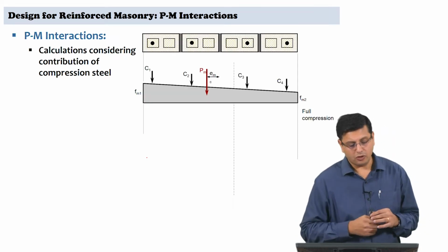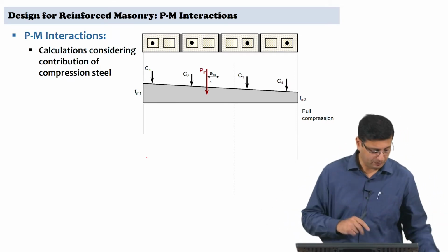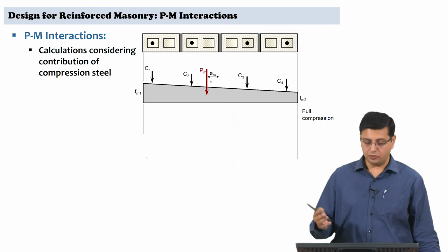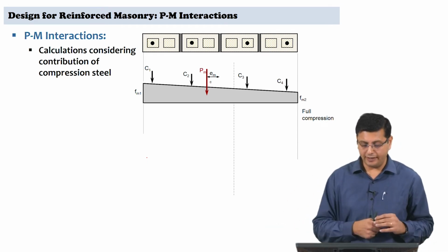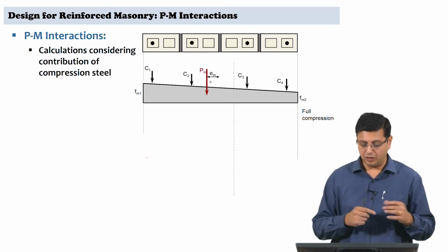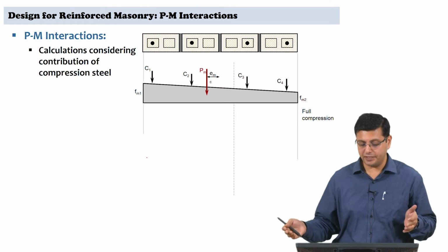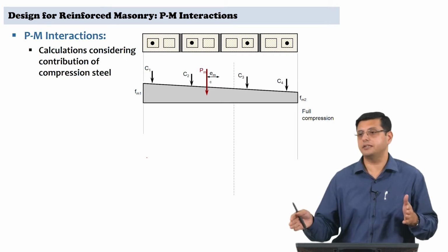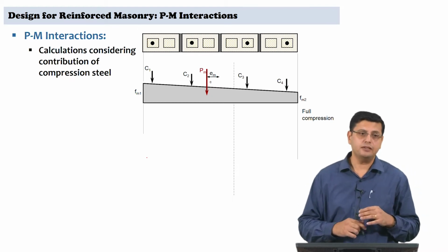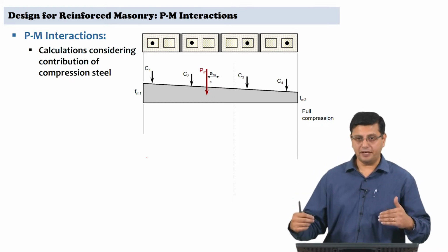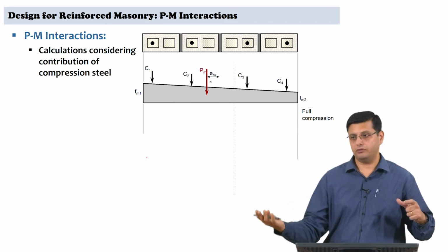Okay. So, first situation, you have the wall that is subjected to a combination of gravity forces and lateral force, in plane lateral force, and so you have a non-uniform distribution of compression. However, the entire cross section is in compression. So, that is where you begin. Your full cross section is in compression.